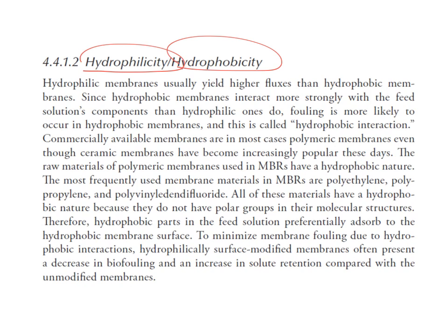When you consider membrane fouling, you first have to consider the concept of hydrophilicity and hydrophobicity. Hydrophilicity means the material likes water. Hydrophobicity means the material repels water. Foulants are normally hydrophobic. If the membrane is hydrophobic, it can attract the hydrophobic foulant so that membrane fouling can readily occur.